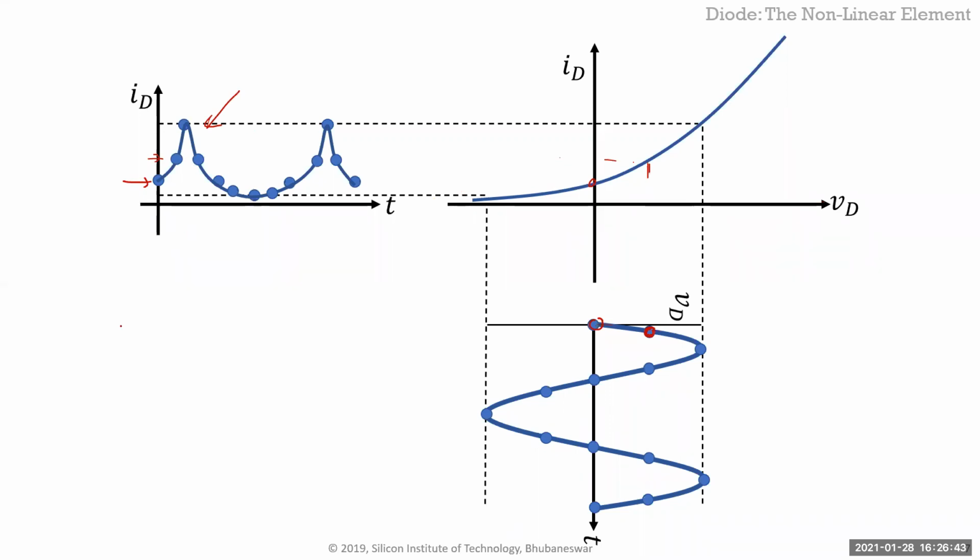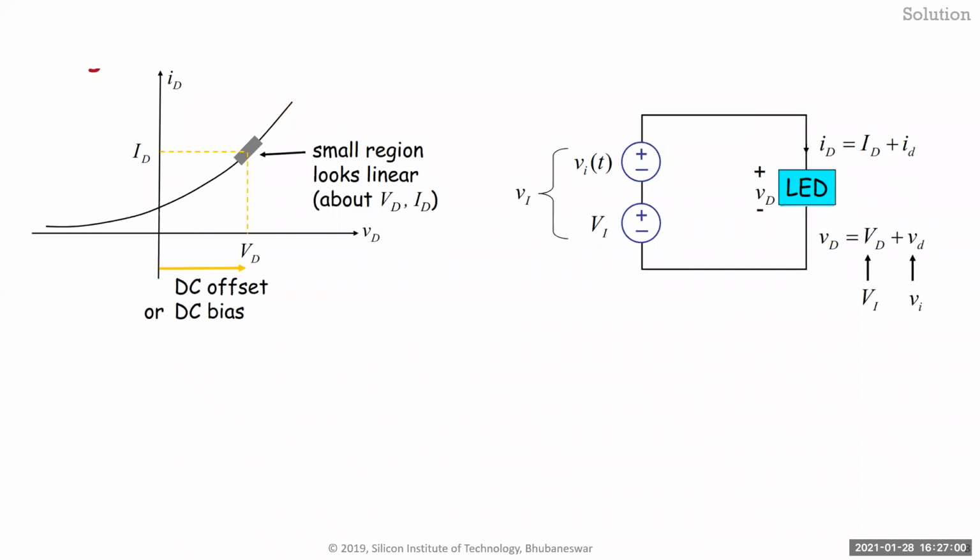And that obviously is clear from the diode equation too, because you have Is to the power VD over VT. And basically this is a compressor, right? I mean, expander. So it takes a small signal, expands it, and towards here, it just contracts it. So that's why you get the distortion.